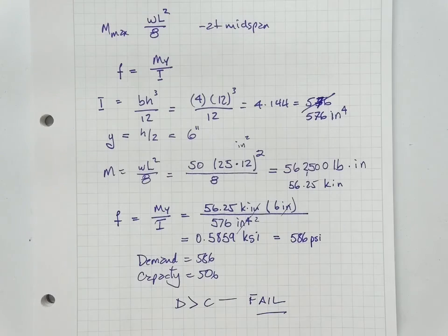The other is, it's always something, everybody knows what VE stands for in construction? Value engineering. Someone says, you can do this, and we can do it this way, and it'll be cheaper than it's been specified, and we'll split the savings. Very common thing to do. You need to know when someone says, hey, if I remove those bars up 2 inches, I could save $10,000. You need to know why that's a really bad idea and be able to tell them. So that's what we're going to work on.